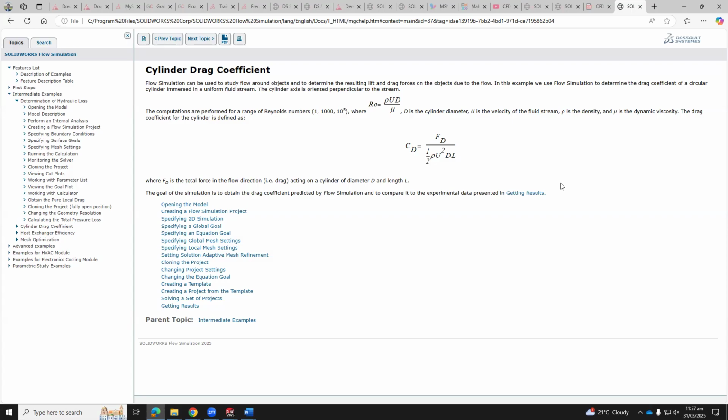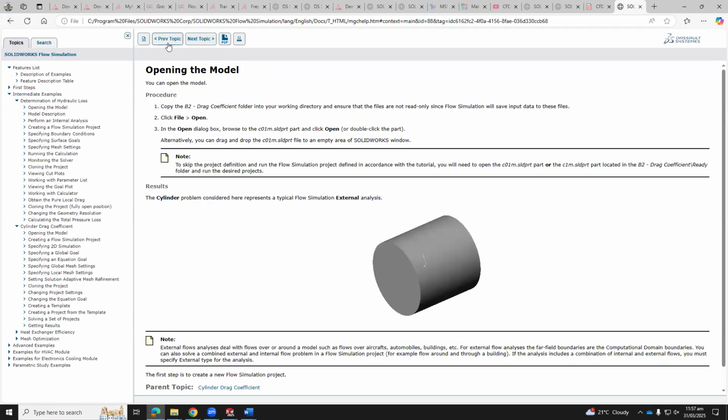So you know the K value, what used to be given to you in a fluid mechanics exam or test? They go to the tables and you find the minor fittings for the valve. SolidWorks will do it for you using that equation. Technically, that equation is very helpful for you. Set it up under goals, equations, and then you go through it.